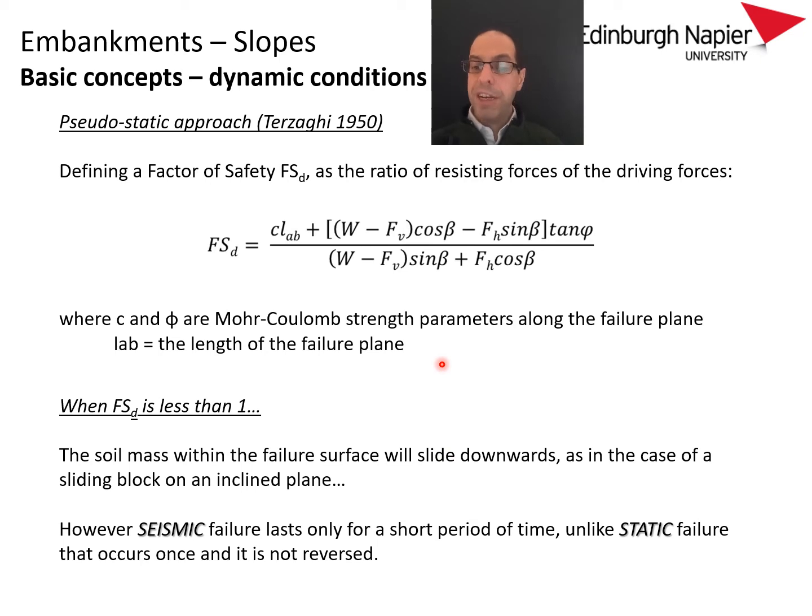But it's still a limit equilibrium approach in which we still compare resisting forces against disturbing forces, and as a result of that we end up with factor of safety equations under dynamic conditions which are quite similar to the ones I was showing you at the start of the lecture with infinite plane approaches.